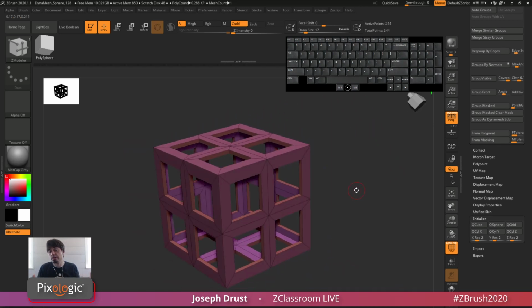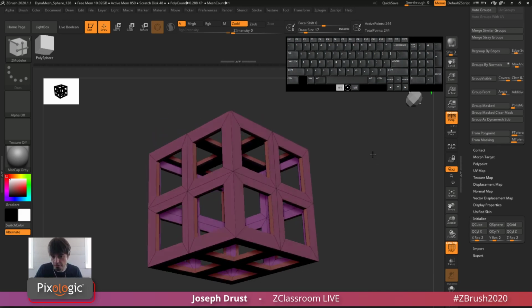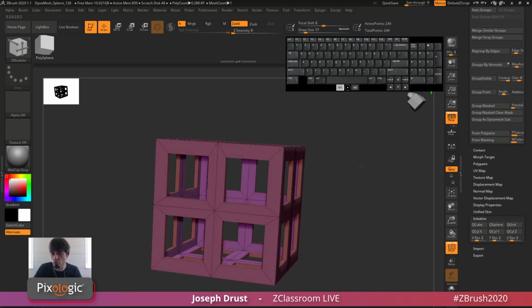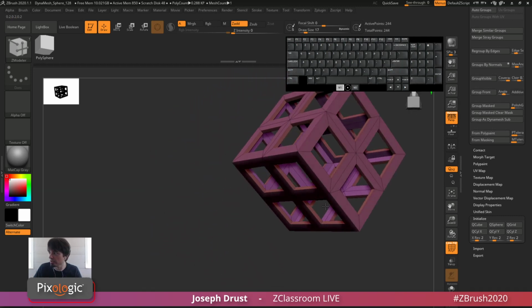So you can definitely do this to create a lattice structure, and it's going to look at whatever the topology of your model is when it does this. If the topology of your model is all triangles and you do that inset, every single one of those triangles is going to be inset, and then you get triangle shapes. Since this one was all quads, when I did it, I'm getting all quads. But that's definitely one way you can go through and make lattice shapes.